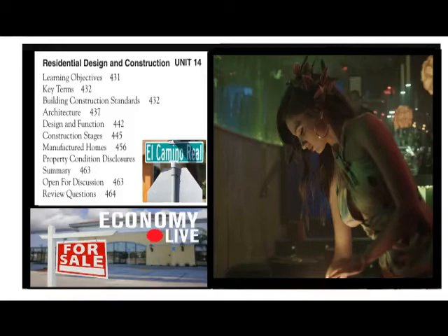Hillside locations, found throughout California, have their own unique requirements. Grading might require construction of retaining walls to prevent earth movement above or below the site. Seasonal water flow might necessitate extensive drainage systems and extraordinarily deep foundation supports.